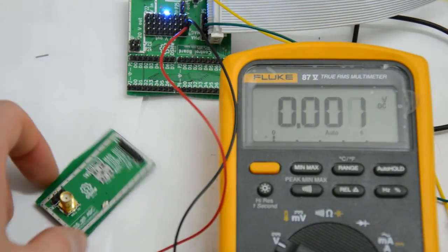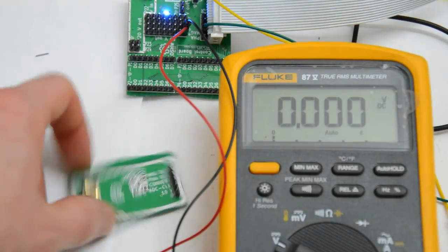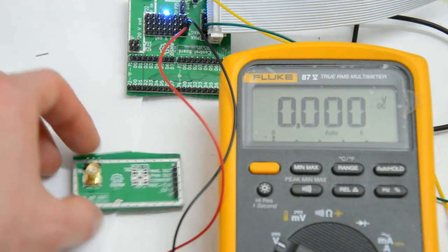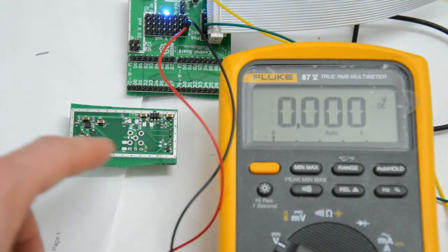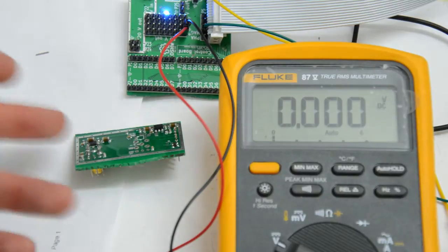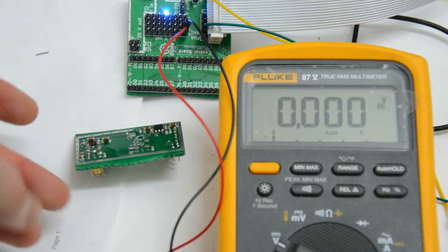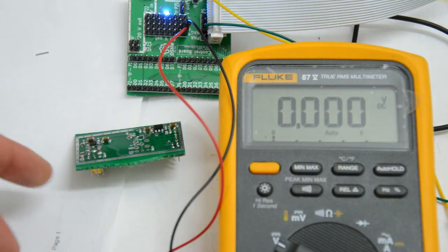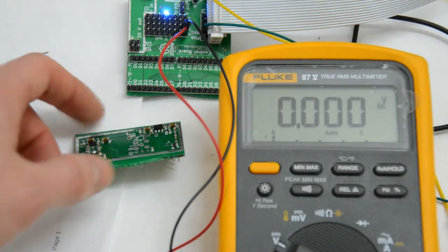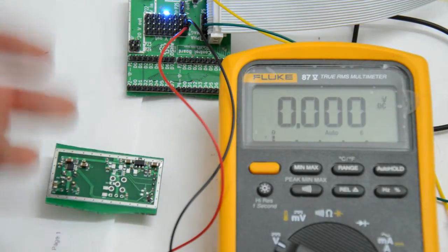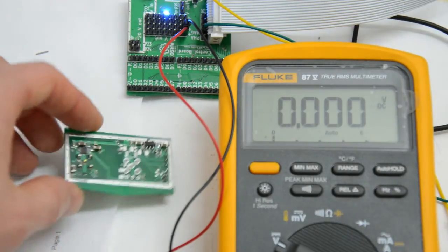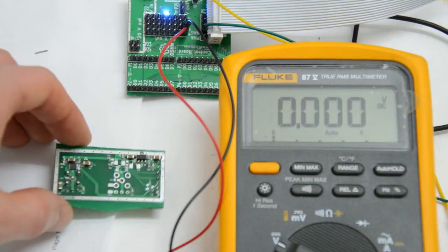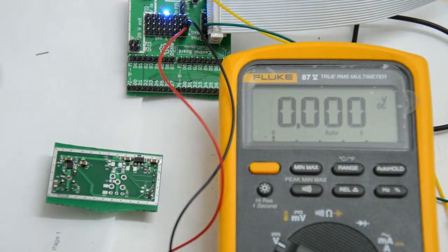Okay, so I built up the ADC board. Here it is. Although as you can see, I only built one of the two ADC sections and left the second one unpopulated. The reason for that is just that the ADC chip is fairly expensive. I think it's somewhere between $10 and $20, low quantity at least, and I wouldn't want to waste one of these ADC chips on a board that clearly has a major flaw. So I'm going to test it with just one, and if this works fine, then I'm going to build up the second one.